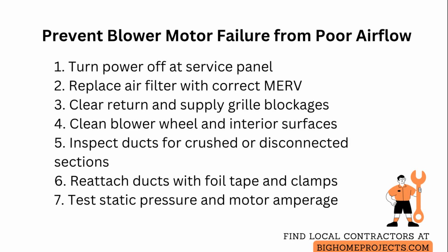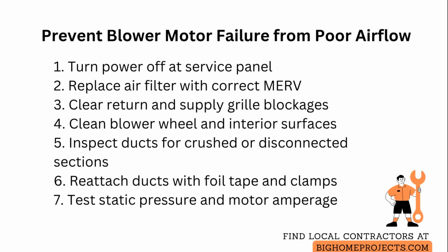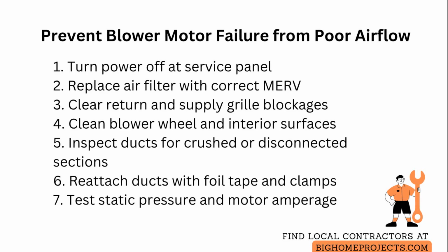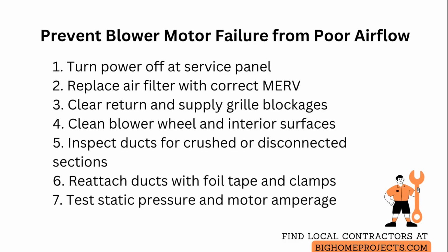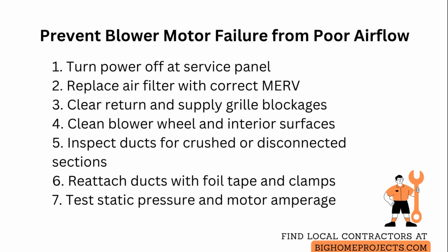Replace disposable filters with new filters of the correct size and recommended MERV rating for your system. Check the return and supply grills for visible blockages like dust buildup, upholstery, or closed registers and clear them so air can move freely. Access the air handler closet or furnace.